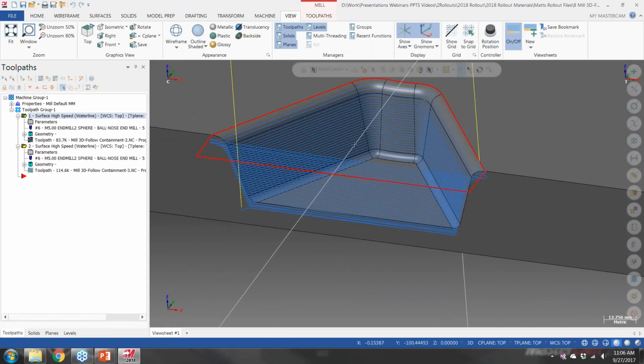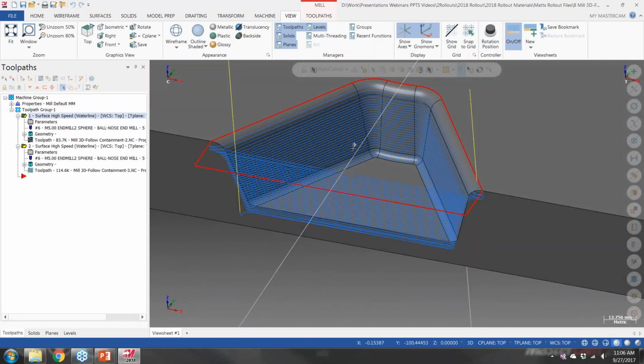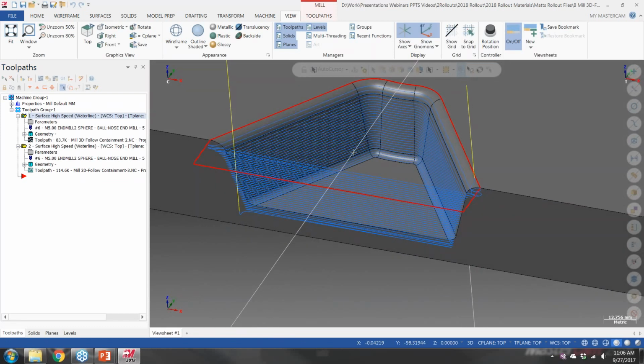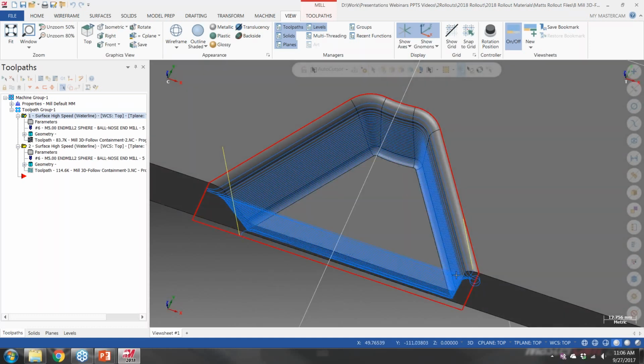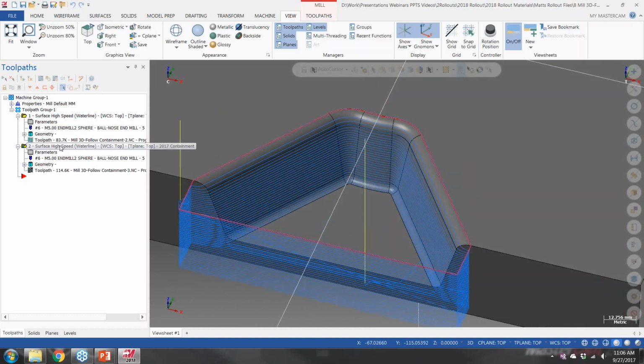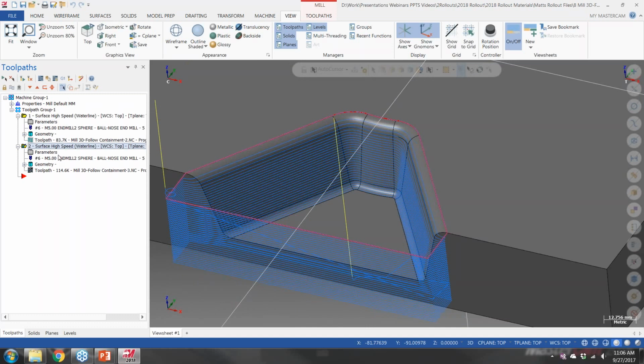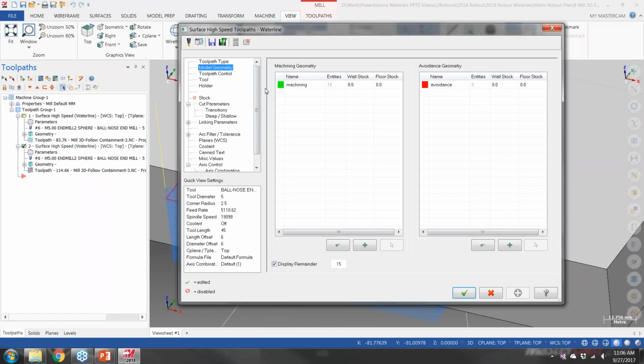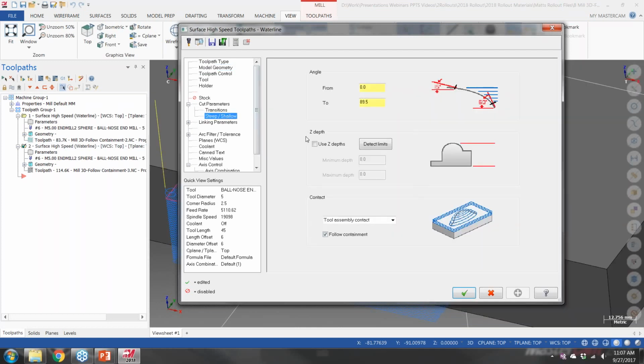So I have two examples here. This is the X9 and 2017 functionality. The feedback was that if you have an older machine that is not the fastest to accelerate and decelerate, you may get some bad results if the tool does a quick motion right away, exiting the material, trying to get to that next climb cut. So we now have the option to do it the prior X8 and before way, as well as maintain the previous functionality in X9 in 2017.